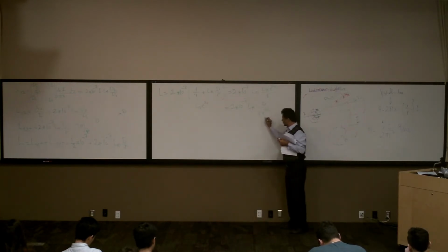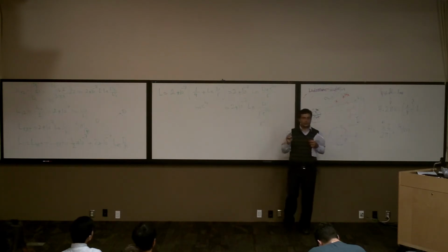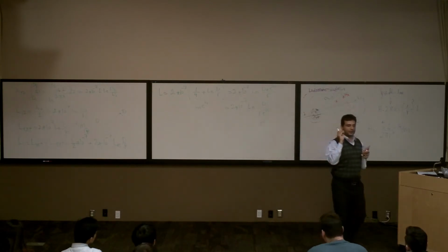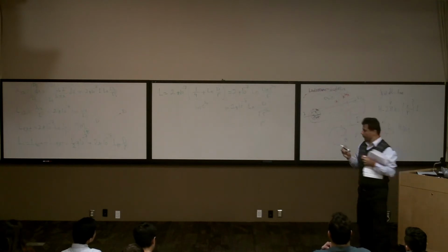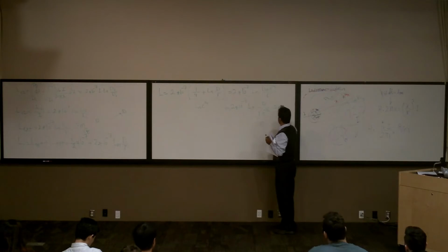This one, they call r prime, the equivalent radius of the conductor. So basically, it's going to be 2 times 10 to the power of minus 7 ln d over r prime.